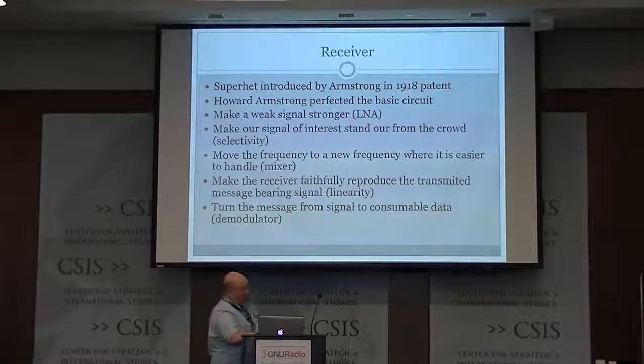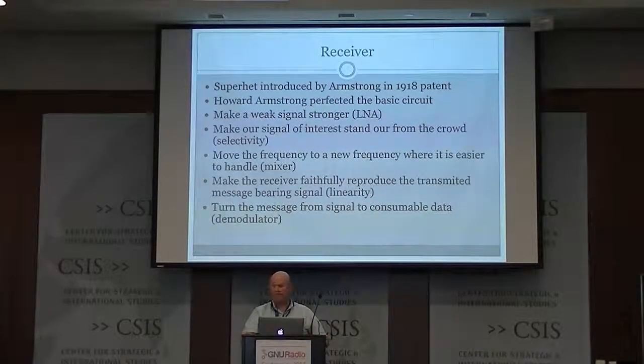Okay. And typically, I have to receive this message after it's traversed a long distance. So it's weak. 1 over r squared is not your friend, and typically it's worse than 1 over r squared in the real world. So not much is actually free space. It's usually r to the 2 plus something or other, especially on microwave bands or high UHF bands where we have cell phones. It's not really 1 over r squared. Free space just doesn't exist where our toys are.